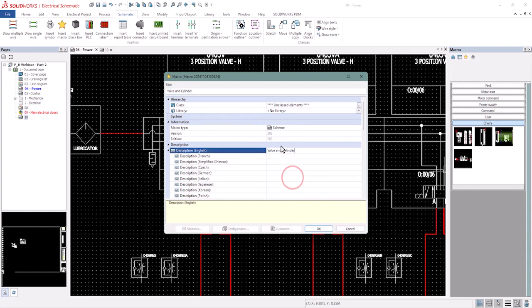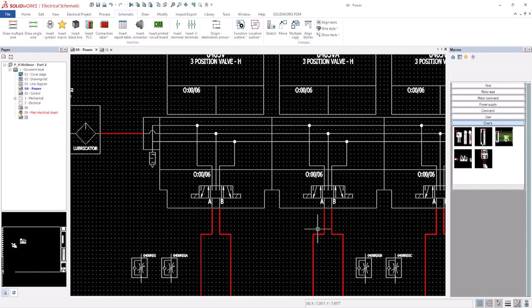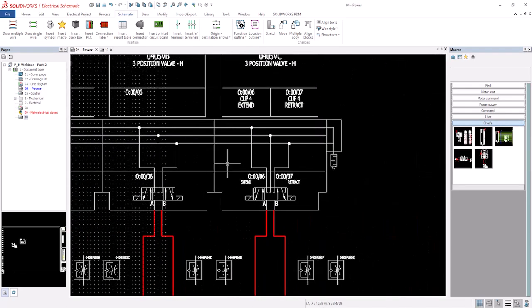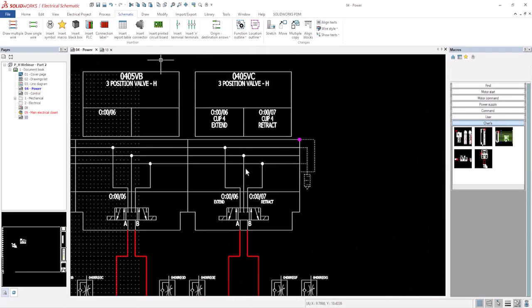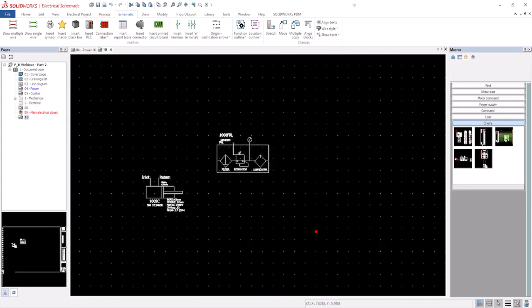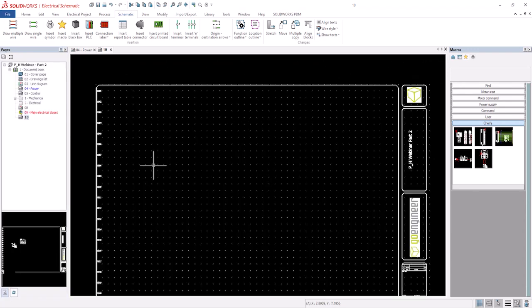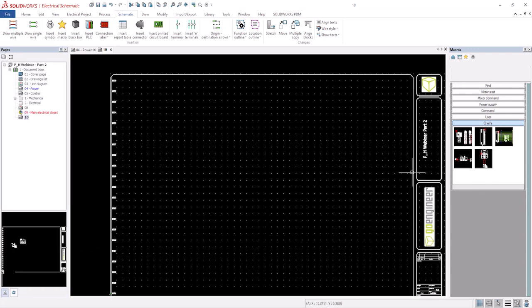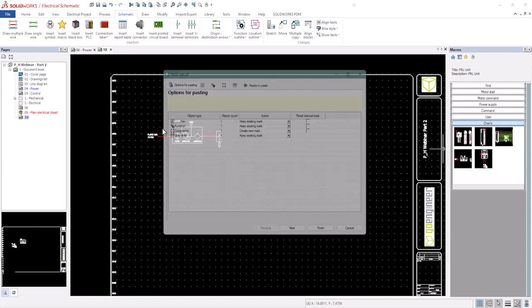So we're going to go ahead and make a macro also here of the solenoid valve and cylinder. And then lastly, of course, I've got this closing muffler. Now, we'll just go ahead and I'll use those macros now. So I'm just going to clean up this sheet and start by just dragging and dropping. So that's all you were doing.